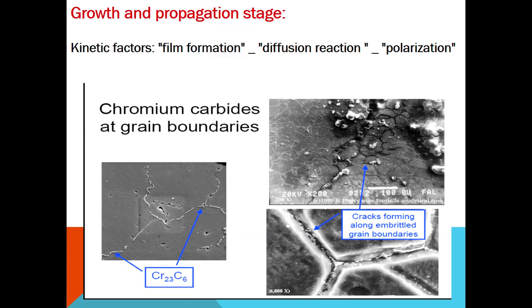Type 304 stainless steel shows highly localized attack. 304 in seawater leads to pitting, and local galvanic action depends on the chemical composition of the matrix and the chemical composition of the precipitates, leading to local galvanic cell action in 304.